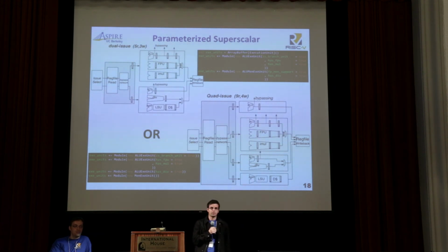Yeah, so Rocket Chip is a whole SoC, a whole computer. What I'm doing is, instead of instantiating Rocket, there's a function literally that returns a processor, and that function returns BOOM in my case. It's like a single flag that returns a BOOM tile. So I'm fitting within the Rocket SoC. However, I'm also instantiating code in the Rocket Chip repository, so it's like a library from BOOM's point of view, if that makes sense.